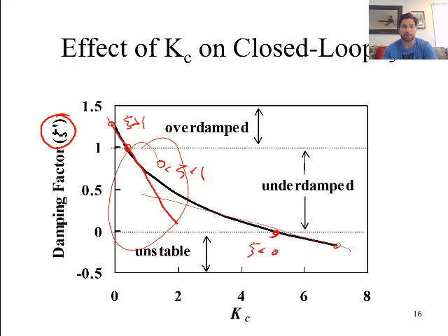Coming back here, you can see that there would be no reason to really go higher for decreased response time, so the range over which the gains are acceptable would be in this range. All right, so you can use these types of plots to determine what are reasonable settings for the gain on the controller performance.